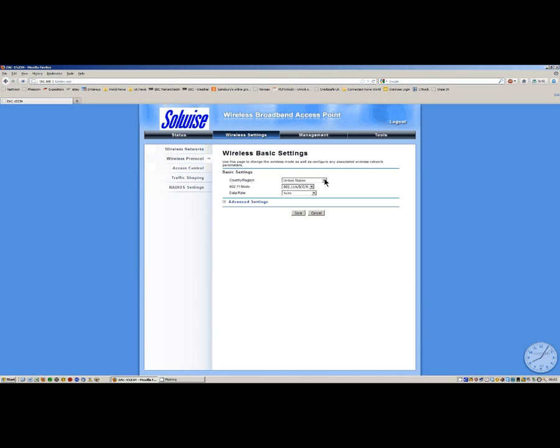As I say, we're particularly interested in using it for leaky feeder cable, where you want as much RF power as possible. So just for the purpose of this demonstration, I'm going to leave it set to United States just to show you what the range of power settings are. You've got the normal 802.11 operating mode, so it now says A, B, G and N. Actually this is universal firmware to suit 5 gig units and 2.4 gig units. The particular VAP unit here is only a 2.4, so although it says A, B, G, N, you can actually just ignore the A part.